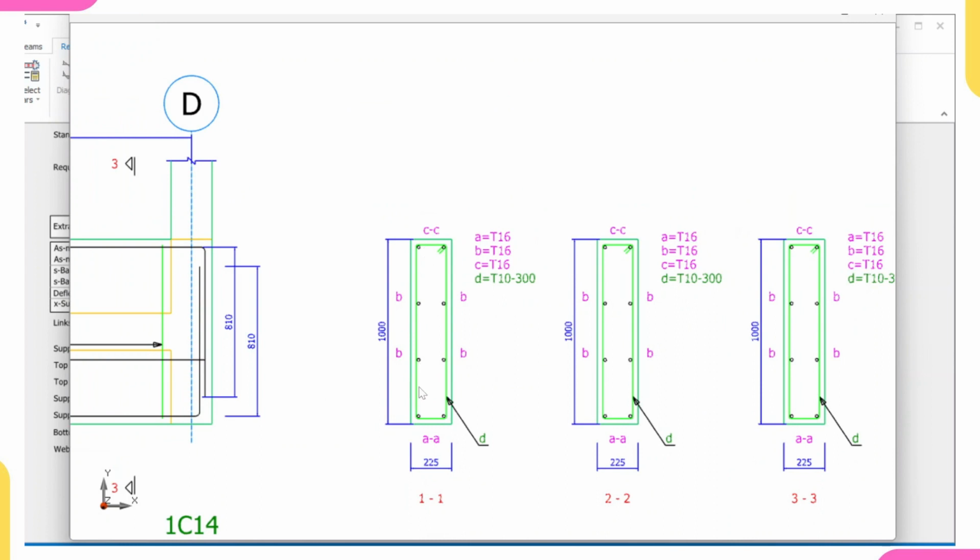The reason for this web bar is because of shear. This is a very deep beam. If I do not include this web bar, this beam might twist, and it will fail due to twisting. To prevent that twisting, we include web bar. So you must include web bar even though the software does not provide it for you, once your beam depth is more than 600.